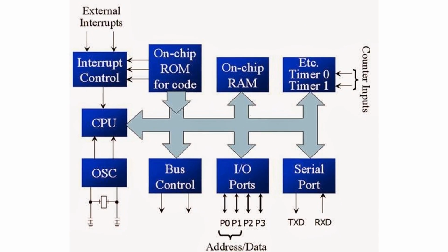So instructions are fetched from ROM to CPU, hence the direction of the arrow is this. And for the others, the CPU executes, and according to the execution, bus control, IO, serial, timers and RAM are changed. Hence the arrow is from CPU to RAM, timer, serial port, IO ports, bus control. And sometimes the CPU reads the value stored in RAM or timer, hence this is bidirectional.